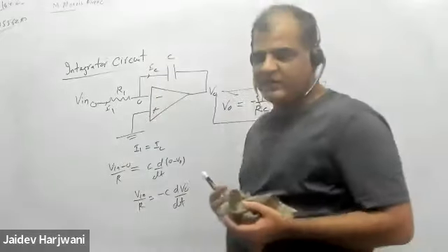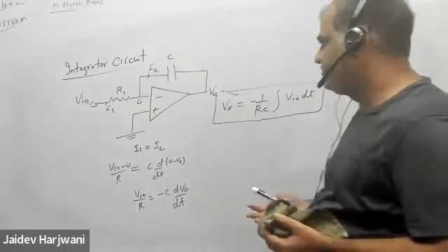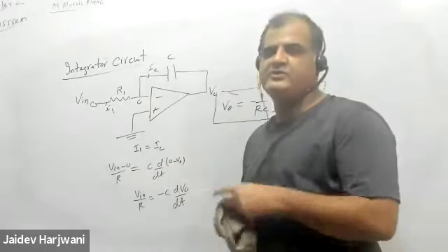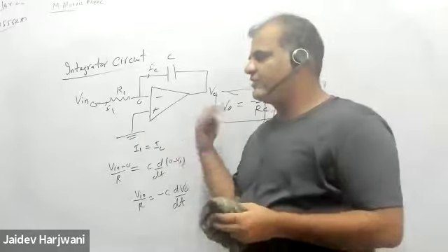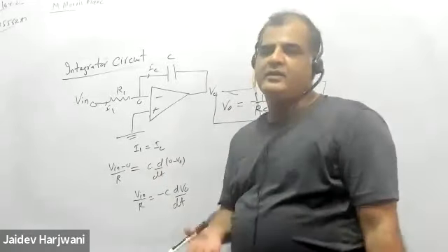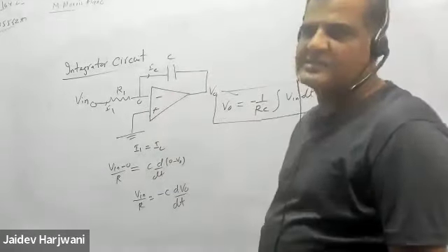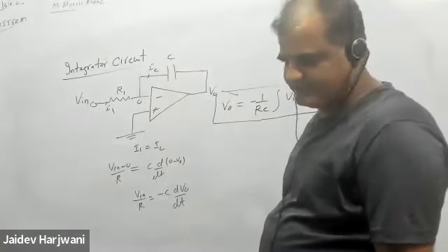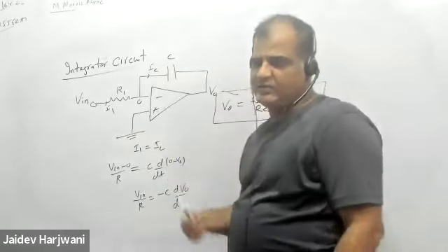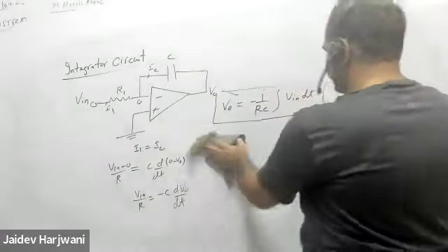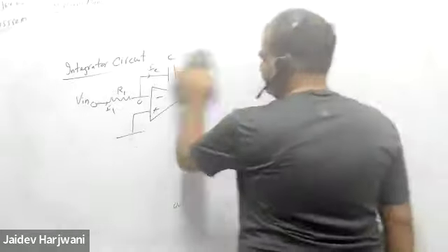Whenever we use op-amp filters, that is called active filter. And if you do the filtering using only resistance, capacitor, and inductor, that is called passive filtering. Because when you are using op-amp, it is not only filtering the signals, but also giving some gain. That is why it is an active filter. While if you have only RCL, that only does the filtration job. So we'll do both kinds of filter, active filter and passive filter.